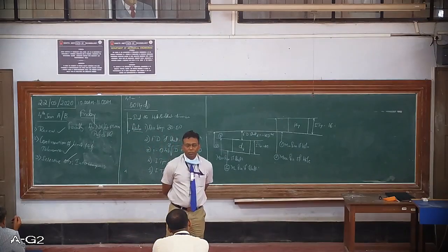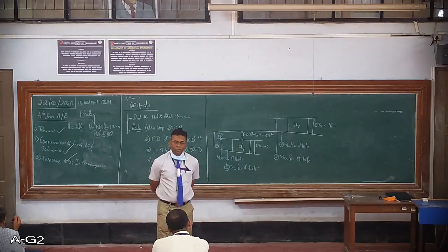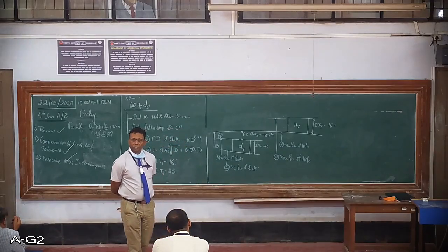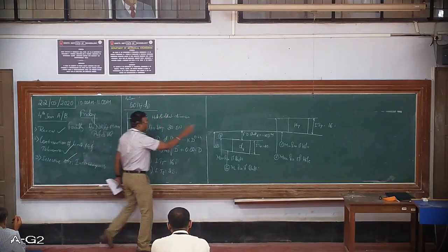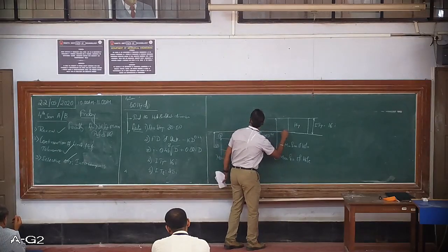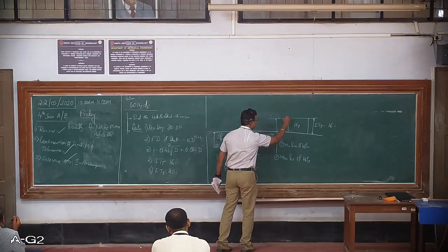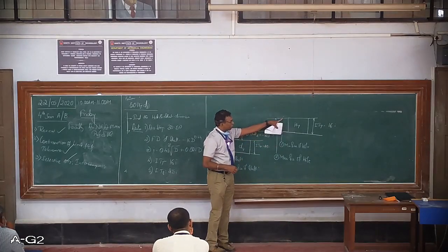Second question, can we still consider it for manufacturing with some modification? Obviously we can do. We can enlarge the hole size, make it into 50 and still use it when the tolerance levels are reached. This is what I mean here. This is 50 mm, this is let us say 51 mm. So this is the minimum size of the hole, this is the maximum size of the hole.